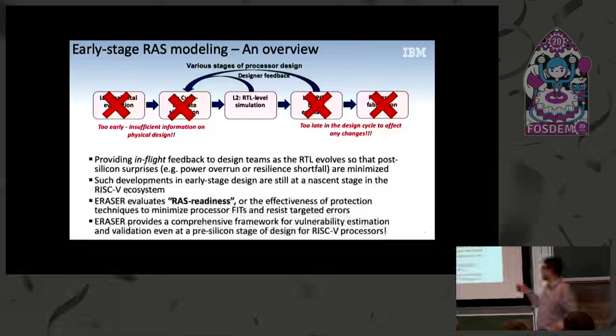It can be argued that you can have some significant design input even at the FPGA stage. But we focus in this case on the RTL level simulation stage. And we can actually look at some of the latches and carry out these simulations and run this methodology to evaluate the vulnerability of latches and proactively make design changes to mitigate them.